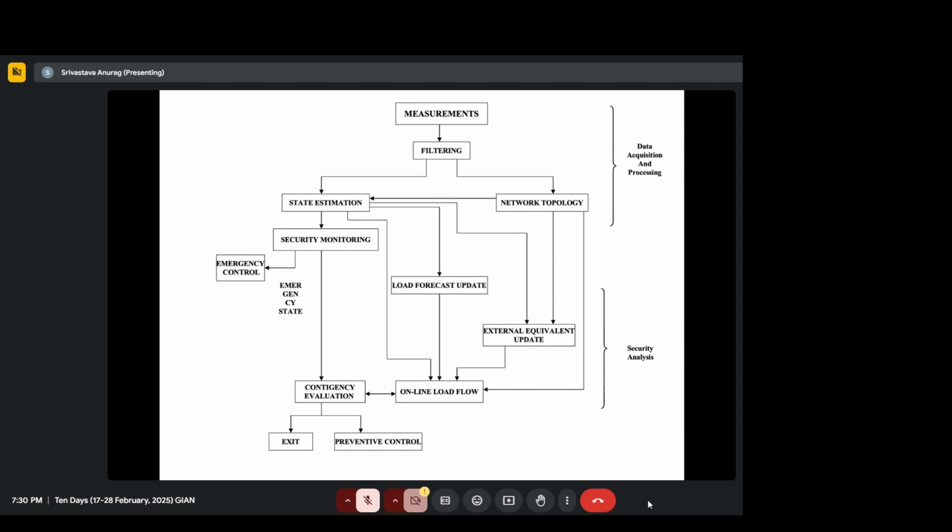That's why we used to select first and then do detailed power flow analysis for the selected ones. And if you want to take a control action, sometimes we need to solve the optimal power flow, which will tell us the control decision. But still, it's needed to narrow down by rough analysis and only do detailed analysis for selected contingencies.